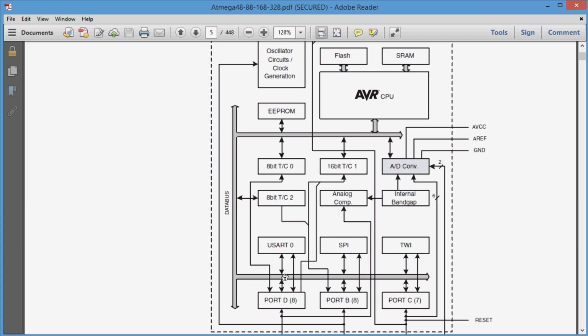What the CPU does is it writes a value to this data bus, and it travels all the way around to these I/O pins, and then it controls these lines here to put those 8 bits of data onto the latch that drives each of the I/O pins. So in this case, you can write a single byte to an I/O port and have all of the I/O pins change at the same time. And that's what I'm going to show you how to do in the software here.